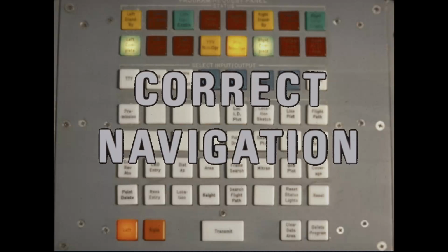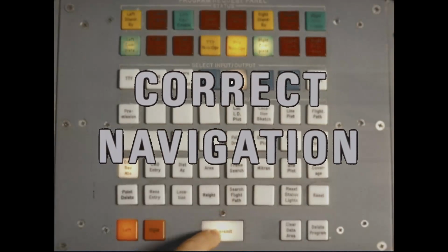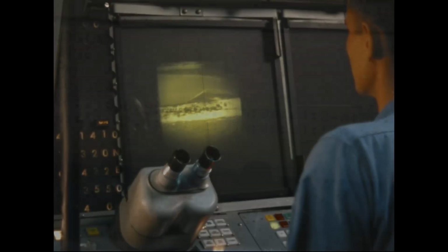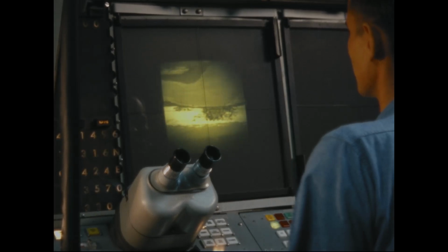The operator now makes use of the correct navigation program. The program calculates the difference between the known actual coordinates and the computed coordinates from information in the code matrix block and stores the corrections. If desired, a teletype output of the corrections can be obtained. In this case, the corrections are 2 minutes, 31 seconds north, 1 minute, 24 seconds west. Where corrections have been made for 2 or more such frames, the correction table in the computer will be used to interpolate for all intermediate frames of photography for the same flight.